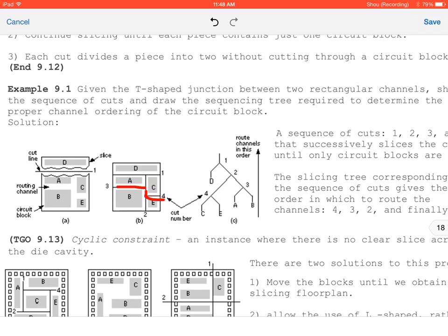Because the whole point of this is we're trying to reduce the wire length. Okay? So if we come up with a min cut, then we can hit every possible part of D. And remember, it's all cut into bit slices that we're trying to optimize that particular area. So if we can come up with a min cut, then we can guarantee that we can get every single part, right? So then we get to these two, we figure out we can, along this min cut, get a straight line to the edge. And actually, I'm going to show you an example here in a minute that should really answer your question in detail. Once we get down here, then it's kind of like, all right, I can see the end here, right?